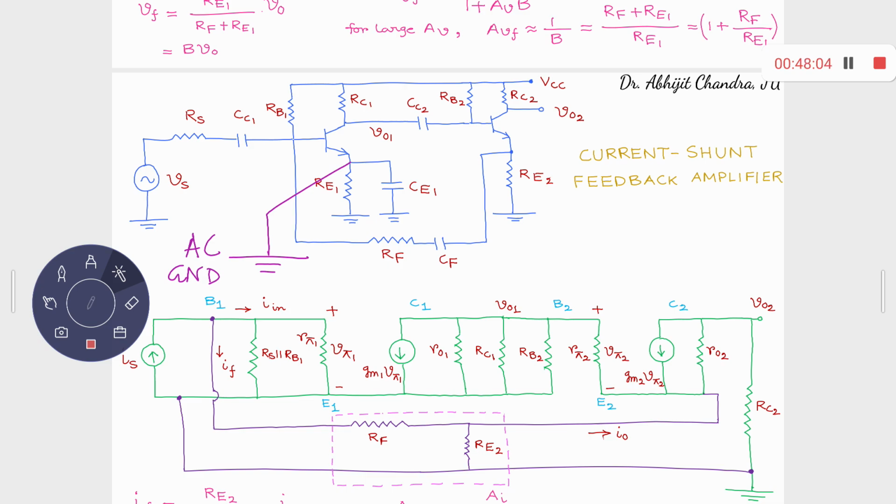You have to understand that okay, it's a current shunt, but whether it's negative or positive feedback, it's a negative feedback. Why? Because base 1 to collector 1, B1 to C1, there is a 180 degree phase difference. C1 to B2, no phase difference because they are connected AC wise. B2 to E2, there is only 0.7 volt drop. So therefore, E2 to B1, you have 180 degree phase difference. Right. So I can simply have a resistance between E2 and B1 by virtue of this particular thing.